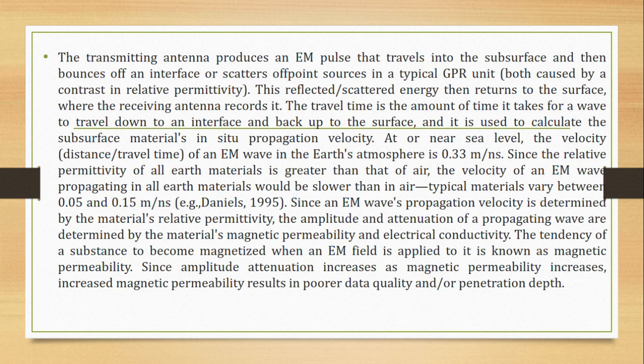The transmitting antenna produces an EM pulse that travels into the subsurface and then bounces off an interface or scatters off point sources in a typical GPR unit. This reflected or scattered energy returns to the surface, where the receiving antenna records it.